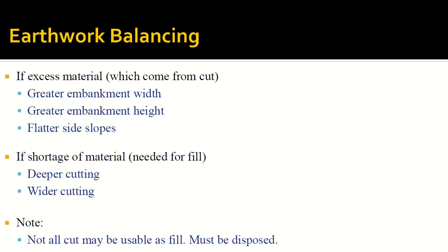So instead of buying the material from somewhere, I'll go to my site and whatever slope I have, I'll try to cut it more, again to make the slope flatter. If I cut it like this, the slope will be steeper and I will have less material. But if I cut it more, I will have extra material now.